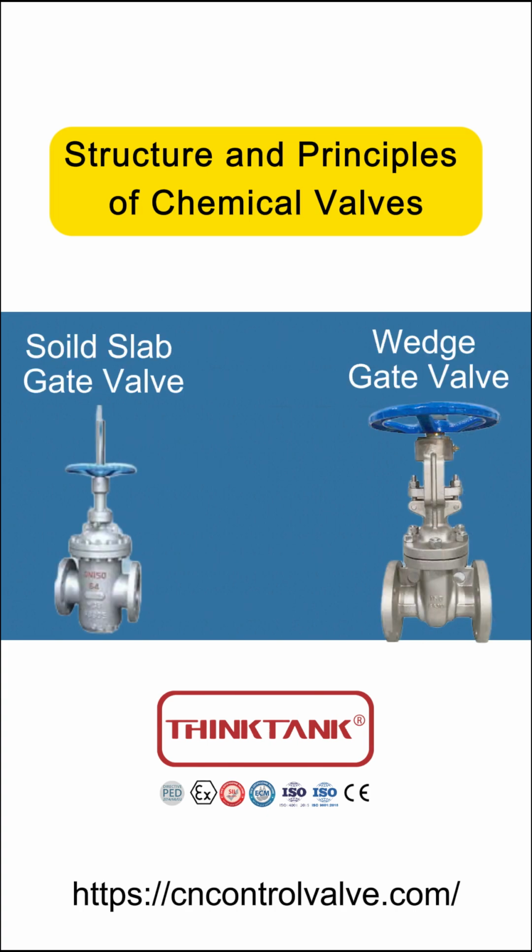Gate valves are divided into wedge gate valves and slab gate valves. Their difference lies mainly in whether the two sealing surfaces of the gate and the valve body are in a parallel state or a wedge-shaped state at a certain angle.